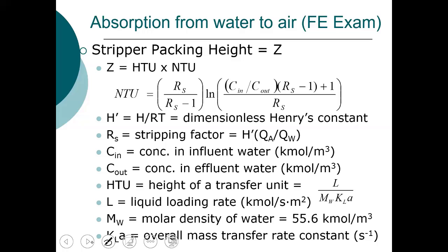And using that approach, when we're looking at water to air, so for instance, we have a contaminated groundwater, we're looking at stripping that contaminant from the groundwater into the air and then subsequent treatment in the air. Why would we do this? Because it's more cost effective in some instances to treat the air than it is to treat the water.